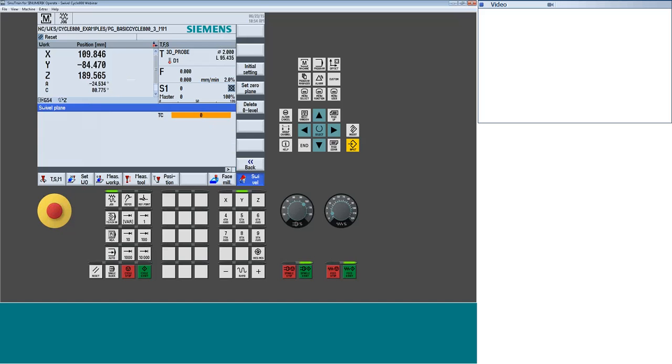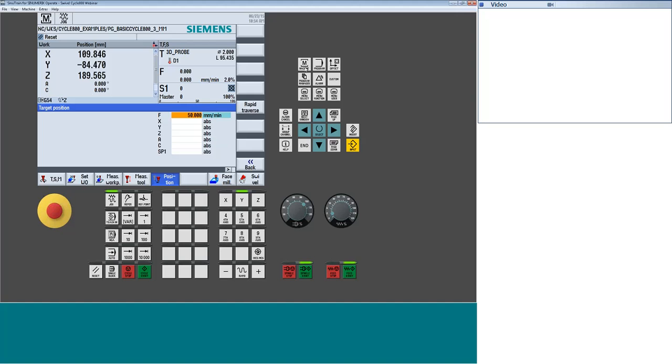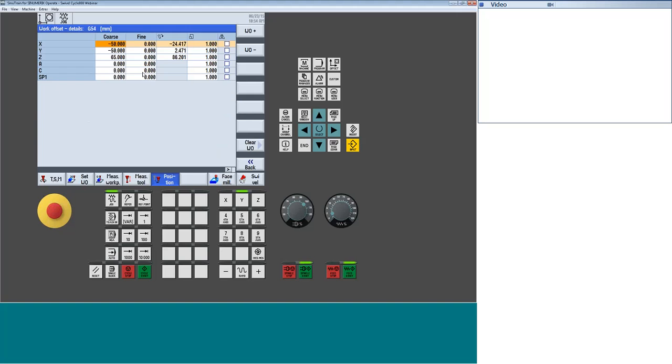So in this case, if I was to position to 0, 0, rapid, if you look at your machine, everything is square, right? It's at the original 0, 0. However, you do still have offsets in play. So you see how this has this little rotational symbol here? There still are values that are coming in and affecting us here because it doesn't delete these values.